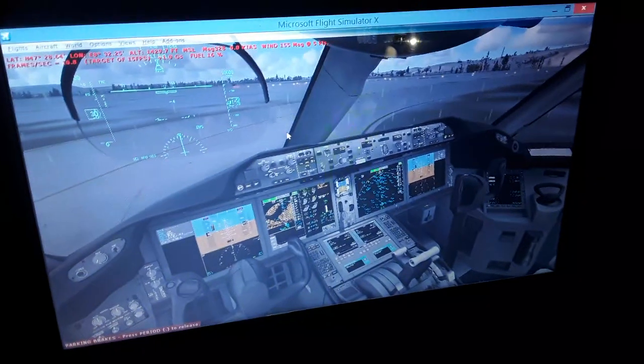So we have also the LSZH localizer crossbar. We have the flight director crossbar for manual guidance of the aircraft and the autopilot crossbar for automatic guidance of the aircraft. We have also the angle of attack of the aircraft as it flies and the flight mode annunciator with the autopilot and the autothrottle. Later on vertical navigation mode, we have also the display that shows the magnetic heading and track.